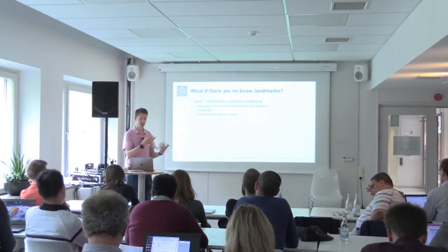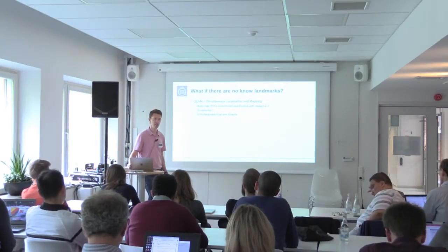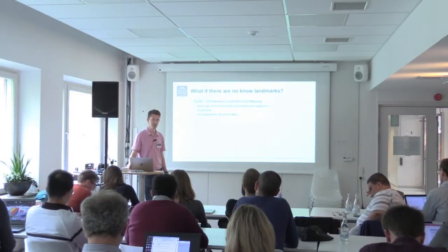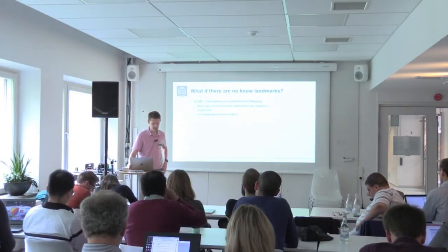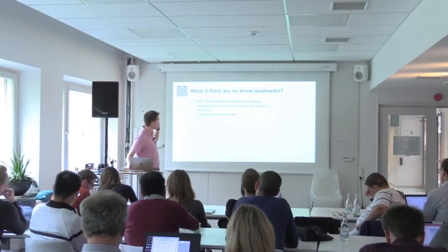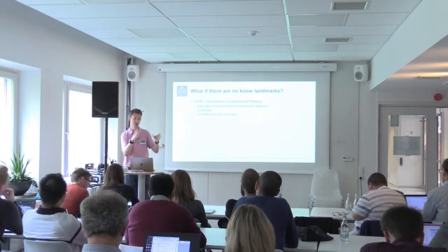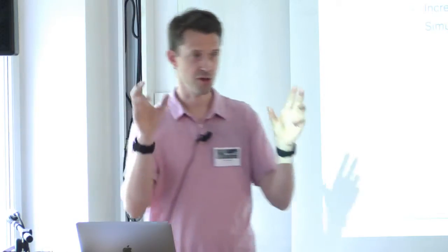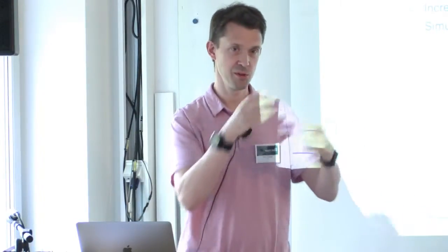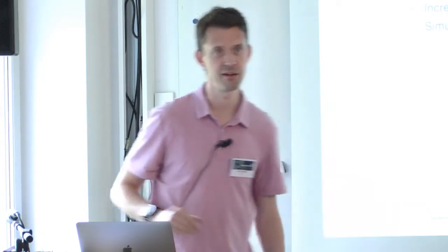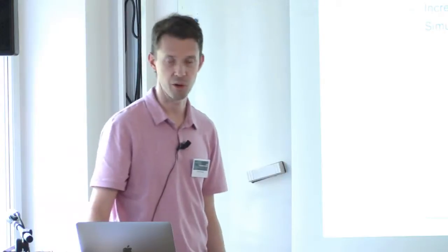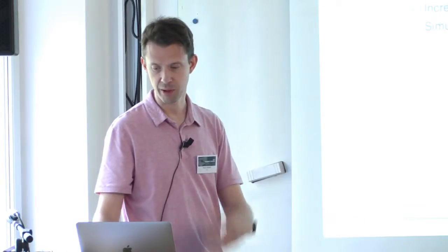Looking back, that seems silly, but they were doing that. So the idea is that we build a map of the environment. As we go along, we use that partial map to localize in. We use our updated position that we got from finding our position in that map to extend the map, and then we go on. So we simultaneously map and localize.